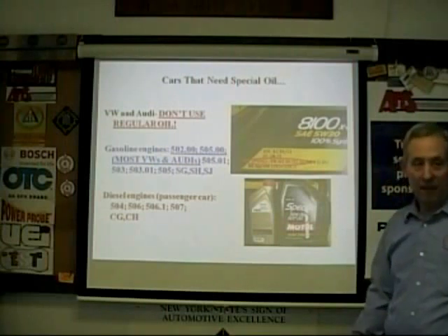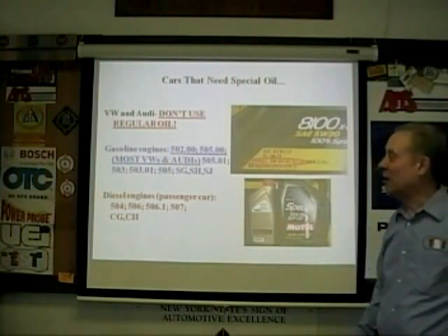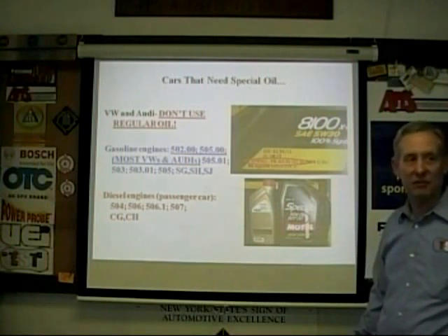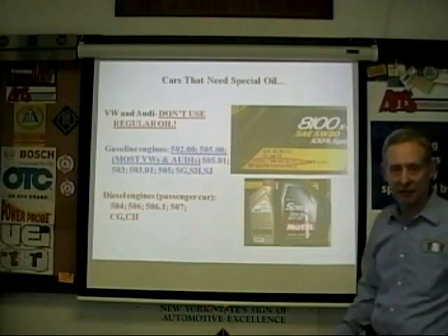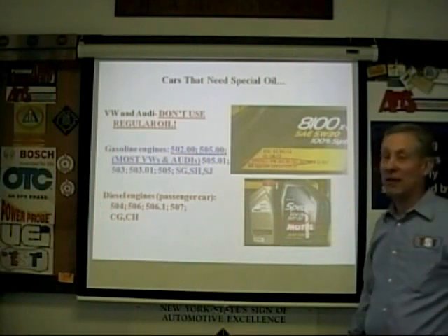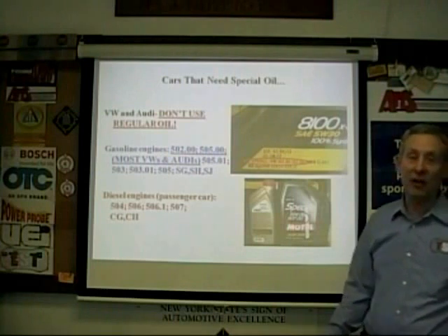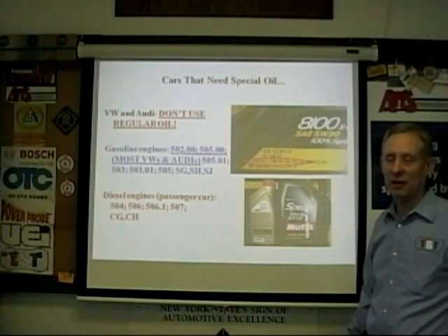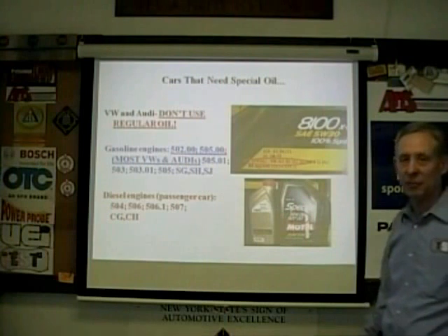And why is that? Because the friction modifiers in the oil are not up to the task of whatever those momentary loads are on those high load devices, cam lobes especially. And Vanos, because there are sliding gears that can bind. Does it have anything to do with sometimes the orifice and a thicker oil? That's a different problem. That's more viscosity related than additive rating related. But too thick an oil will block passageways that are purposely made small for quick pump up times.